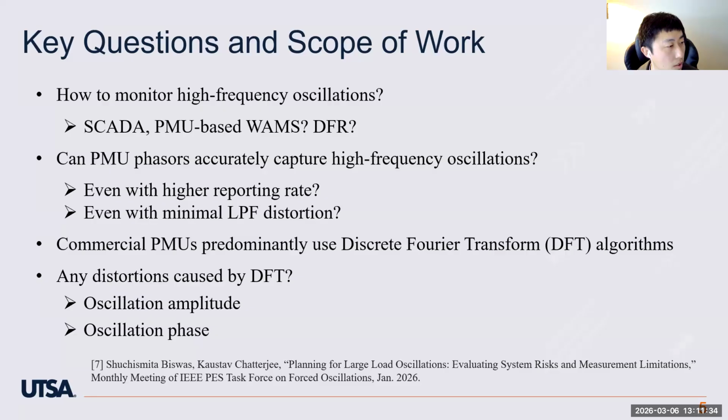First, think about what algorithm or what is the process in PMU, especially the phasor estimation algorithm. If you look at the commercial PMU products, the DFT-based algorithms are the dominant method in most commercial PMUs.